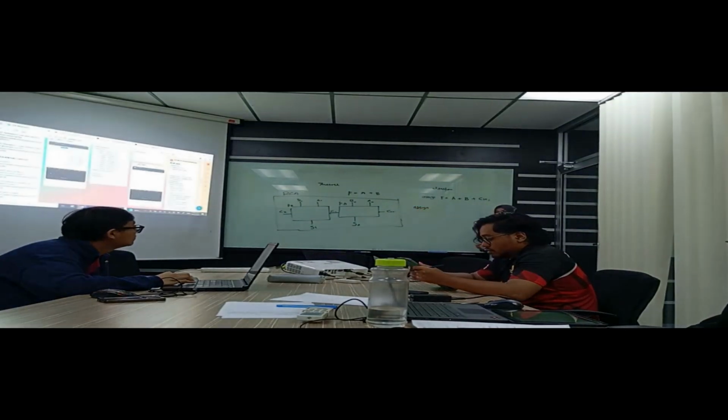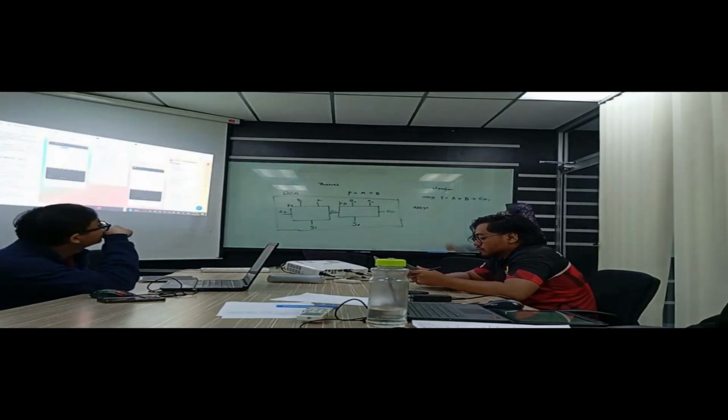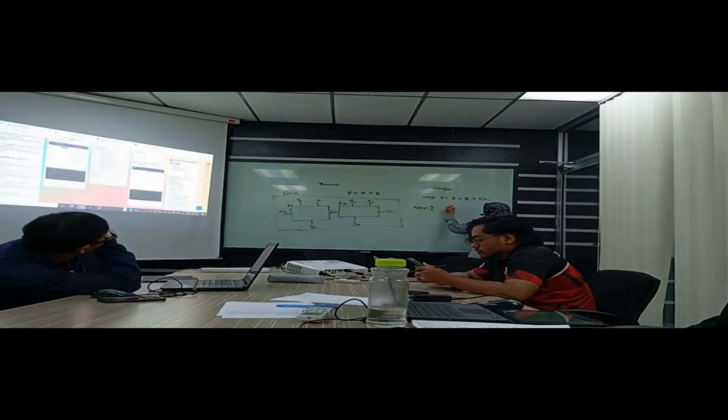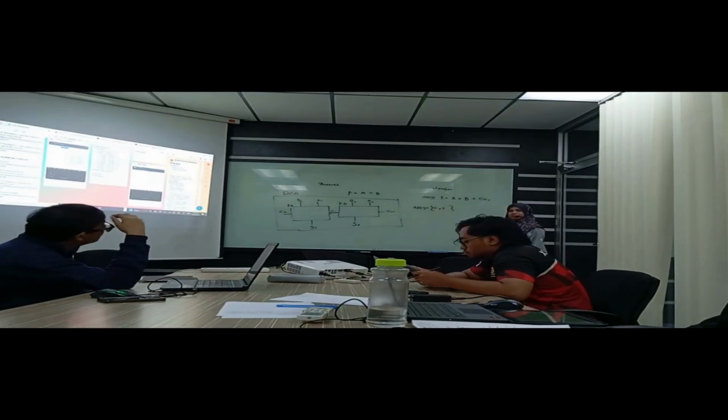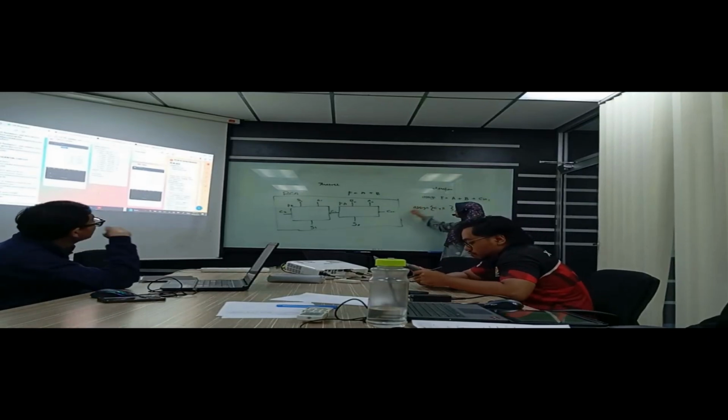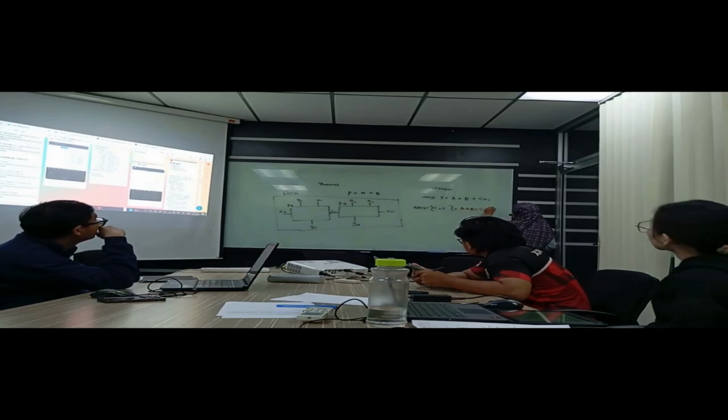Assign, then you have to concatenate: C, comma S, because it represents the C and S. So C, comma S equal to A plus B plus Cin.